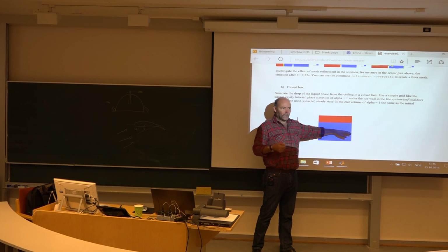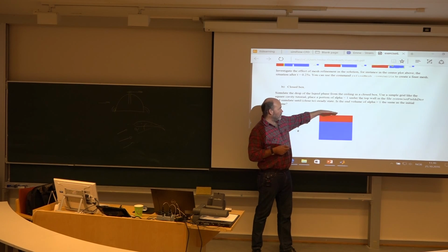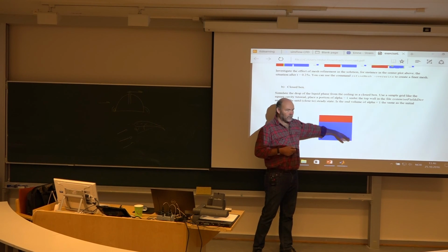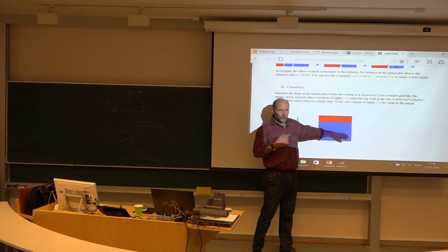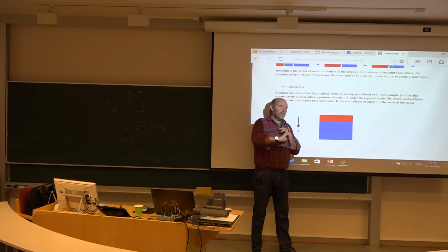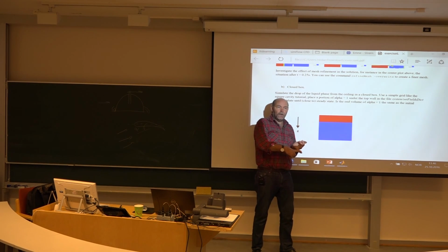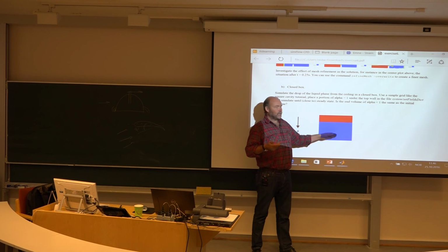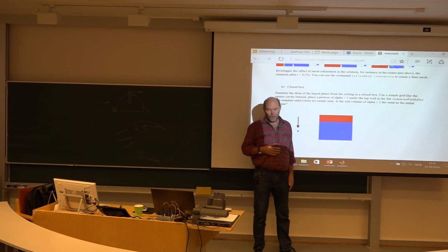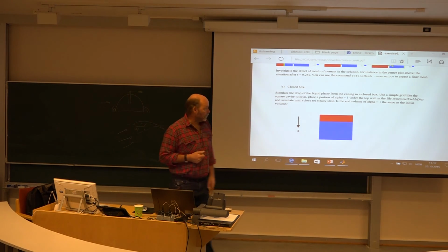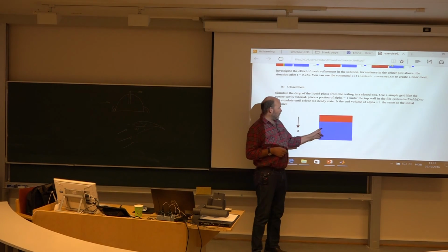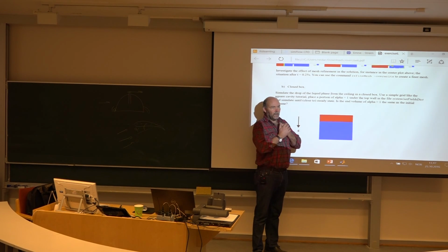So there you might think of cheating, meaning you simulate, say, 10 seconds. Then it should have fallen down and start sloshing around down here. Then you stop the simulation, change, say, the viscosity, and then continue. So then you can make it much more viscous. Then it should settle much faster, for instance. But play around with it, see what you can make of it. It should be quite conservative. You shouldn't lose mass during this simulation, but test it.